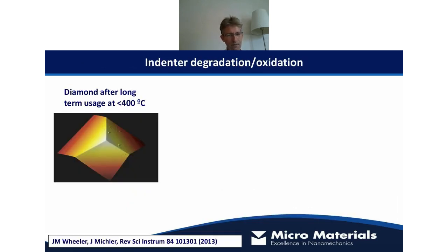So moving on now to looking at the indenter. Diamond is a very popular choice because obviously at room temperature it's very hard, it's very durable, it wears very minimally. And this is an example from a paper from Wheeler and Mickler. This is an example AFM image of an indenter. I think this one was from the University of Cambridge. And this has been used for an awful lot of testing, but at temperatures under 400 degrees.